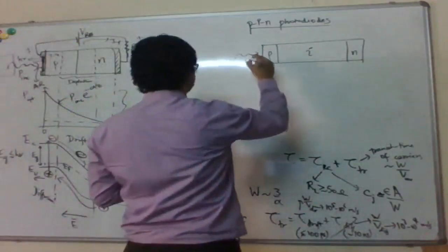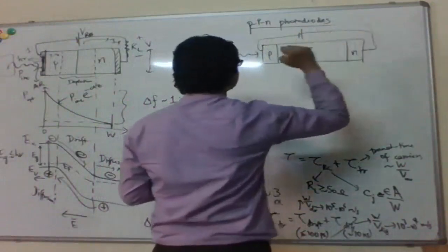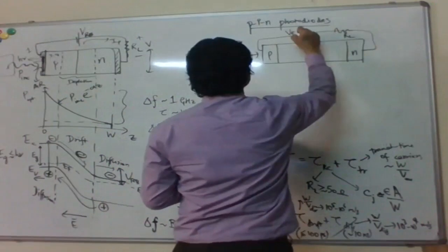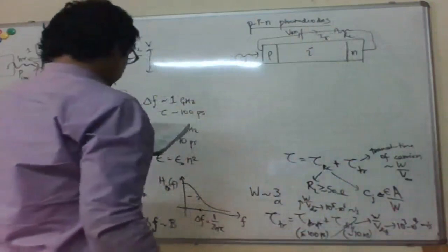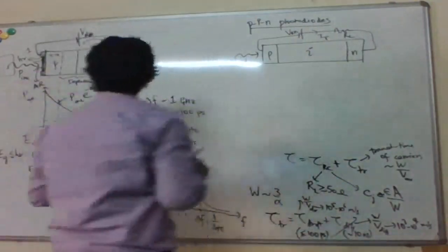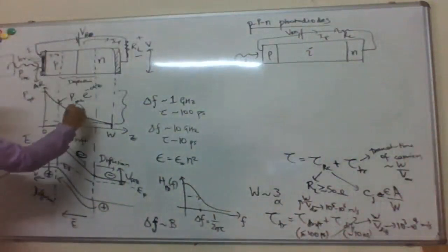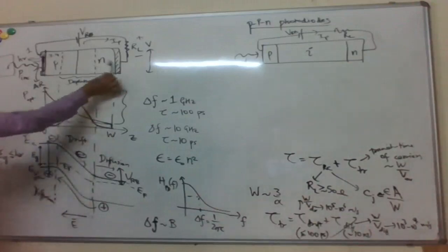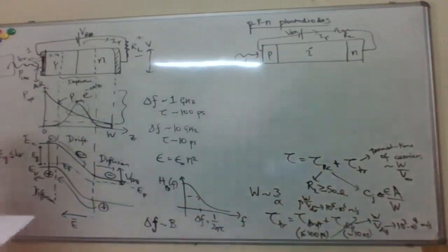And now let's say you have light incident. And again you have reverse bias here, some load resistance here. Photocurrent generated. Okay, so here basically, if you look at the electric field, that electric field was high in this depletion region in between, and then sort of very low or non-existent outside the depletion region. So the velocity was high only in the middle of the depletion region.